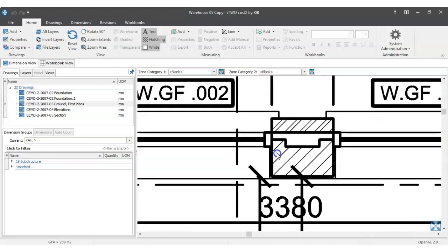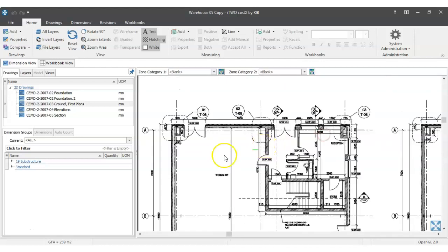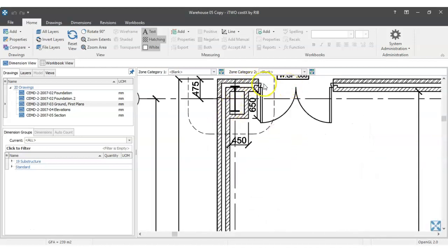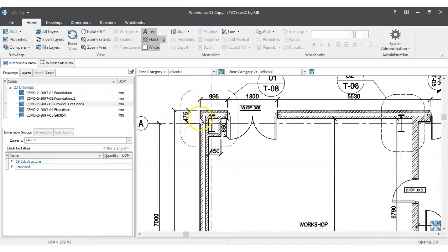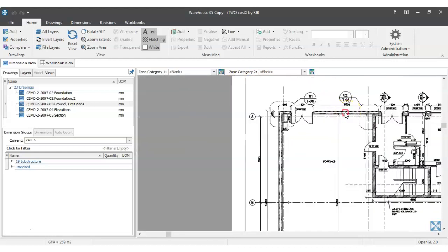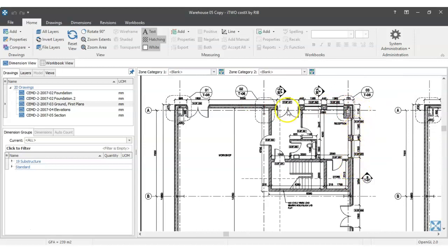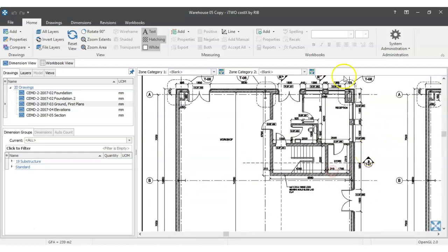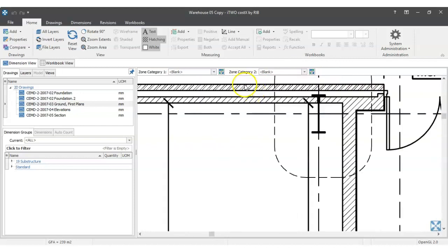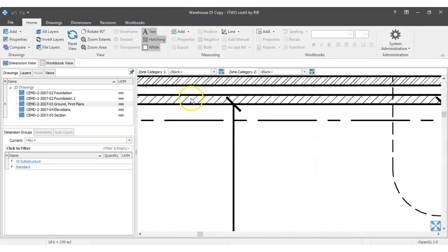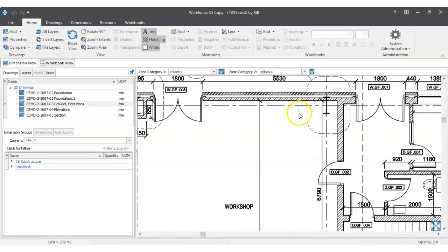So what have I got here in terms of external walls? If you can remember from your takeoff at FICRA, you've got a brick facade, or let's say outer leaf, in terms of the external walls on 2 sides of the elevations of this particular building. So if there's 4 elevations, obviously, we've got 2 sides that have brick facade. Now that's just the outer leaf. We've got a cavity with some cavity insulation in there, and we've got 100mm blockwork internal leaf.